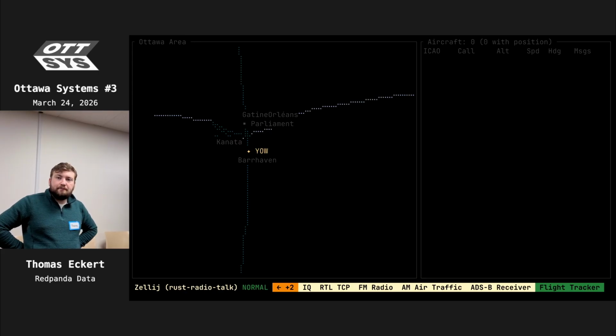It's a sine wave or cosine wave, whatever the case is, just playing by itself, nothing's happening. When you add sound to that, it causes that fixed carrier frequency to gain and lose amplitude in proportion to the audio. So you can imagine the carrier frequency going up and down at unit size 1, for the sake of argument. When you're doing nothing, it's at size 1. When you have some amount of audio added, it goes to size 1.5. You play louder, at size 2, so your peaks get higher and your troughs get lower.